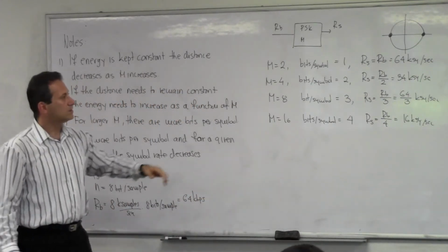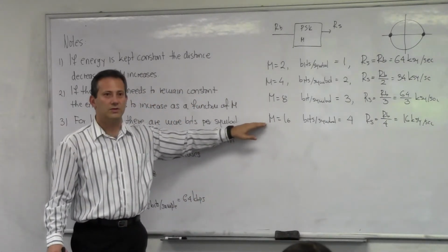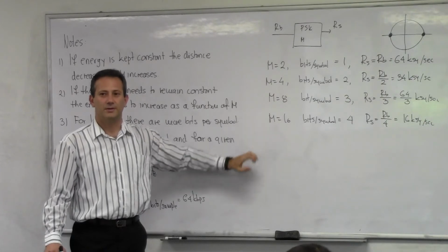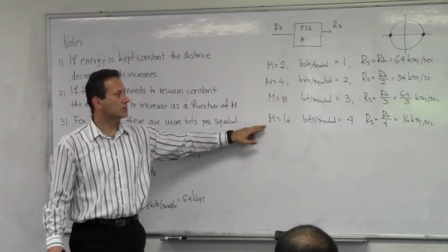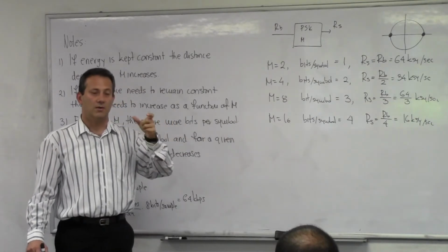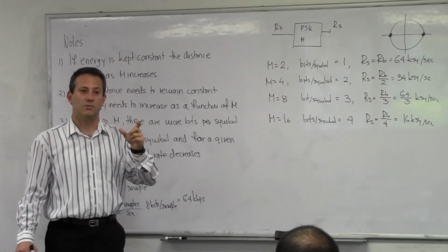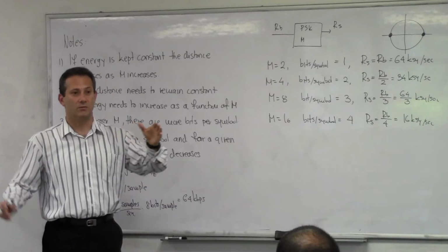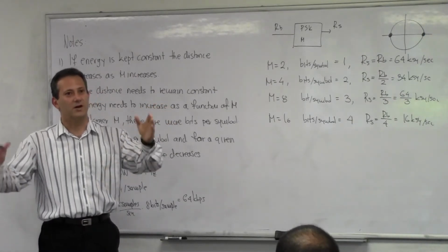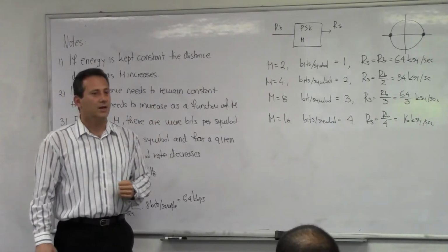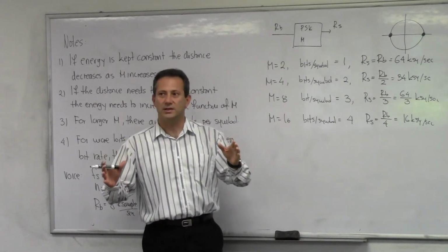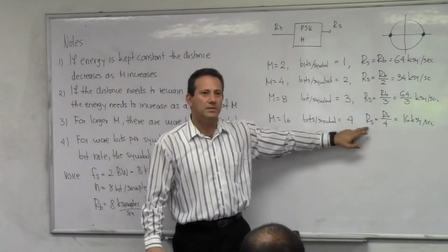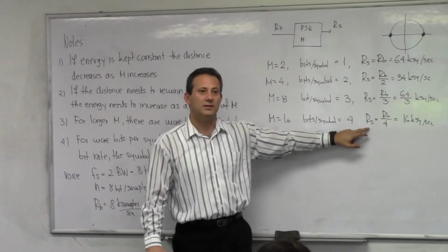Okay? Why is this important? Not at this time, it's too much of a stretch, but it's going to be important for us because one of the things that we always need to show for modulation is what is its spectral footprint, how large is its spectral domain. And what you find out here is the bandwidth of your modulated signal is going to be dependent on this rate.